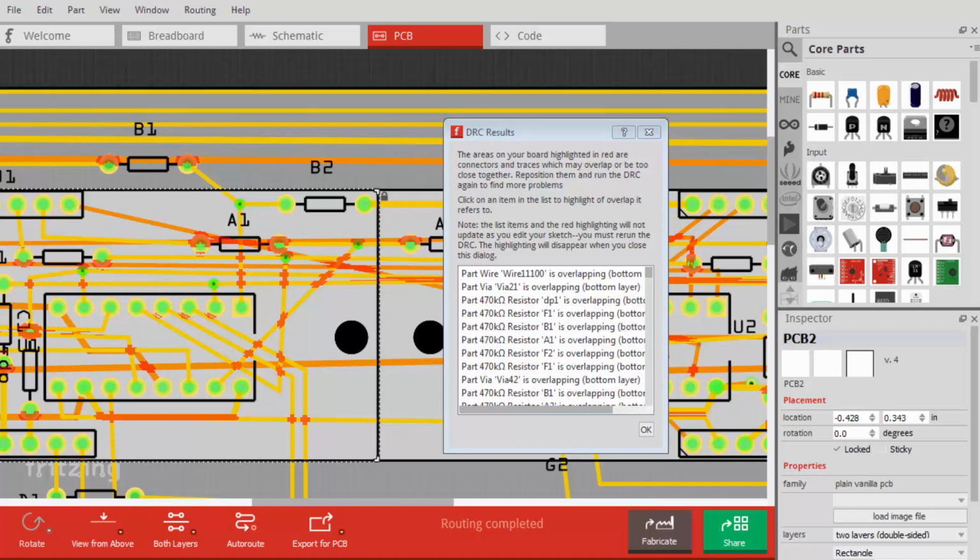In part 4 of our series, we'll look at vias. They'll help us solve a lot of those traces that are crossing each other on each side of the board. We'll also mess around with a tool that is our design rules check. It'll tell us whether any of our traces need to be moved one way or another. It's a great tool that spots our errors and points them out for us. I'll also take a little bit of time to show you how we can add an image, a bit-mapped image, to the silkscreen layers of our boards.